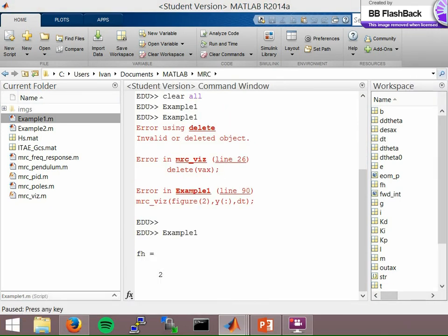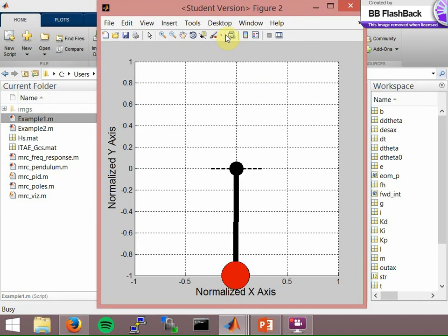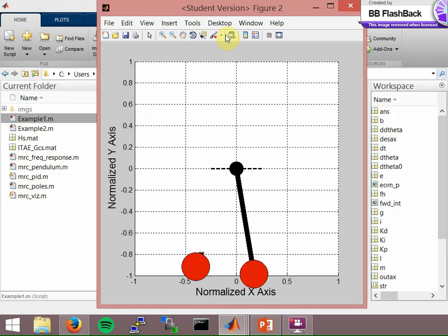Okay, here we go. This is just a system that has a poorly tuned controller, right? So we're not able to actually get our pendulum up to that upright position that we want it to be at. What's happening is that we have a control system that sees that there's an initial offset in the pendulum of, let's say, 1 radian. So it's trying to compensate for it. So it gets up to that desired 180 degree position, but it overcompensates. So now we've gone a little bit further. So when we double back, we've actually gone further than 1 radian.